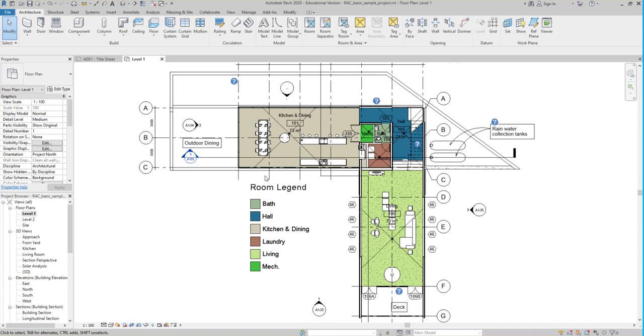Okay? To add another layer to that, that cut view is what you see in the floor plan, and the thicknesses are also related to the field of vision that you see, right? So if you take this building, you cut it at 3 to 4 feet above the floor plate, and you look down, the things that you cut first are going to be the heaviest. And that would be, generally speaking, the walls, the doors, the windows, right? So if I cut it 4 foot here, I would hit the window, I'd hit the wall, the window, the wall, all the way around the room. Those would be the heaviest thing, right?